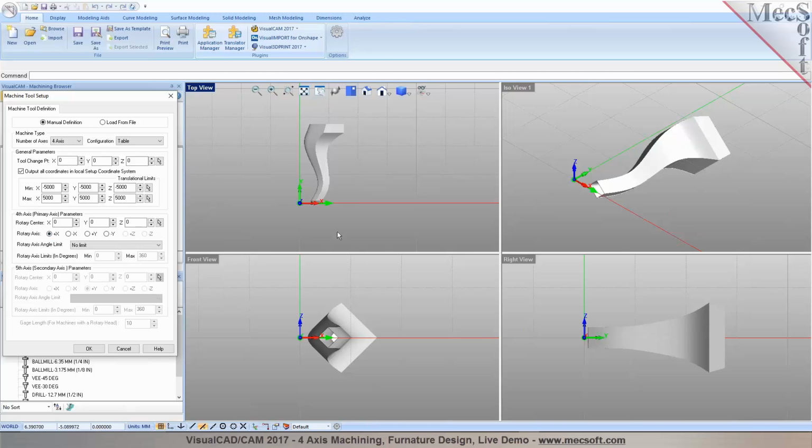So when you select parallel to X, you could be defining the rotary axis positive X or negative X. So a typical scenario for a positive X would be the rotary chuck is over on the left side as you face the machine tool, and your rotation direction arrow, as you can see, is along the positive X. Which means as you point your thumb in the direction of the arrow and roll your wrist towards you, that would be a positive, like a clockwise rotation, and then the other way around is a counterclockwise rotation.